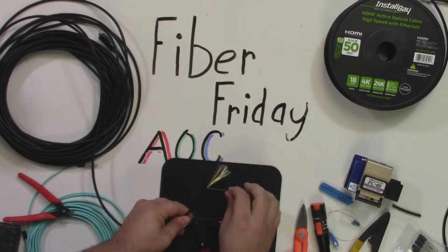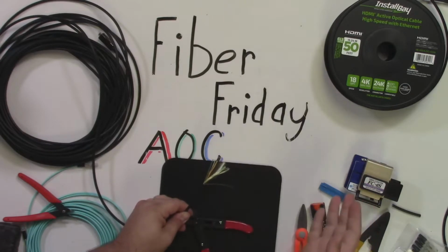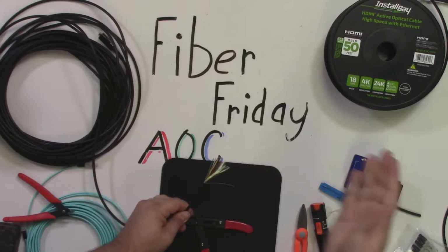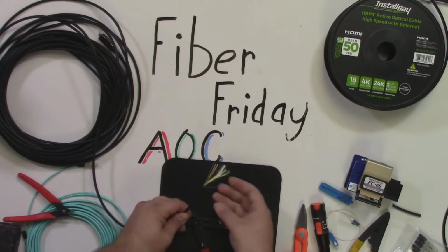So right there, this piece here isn't just for strain relief. This is actually one of the grounding wires from inside of the HDMI cable. This is used to ground from the TV or the sink back to the source or the Blu-ray player, whatever it is. Which is important for the EDID and the 5 volt and the hot plug. Exactly. So you have that there.